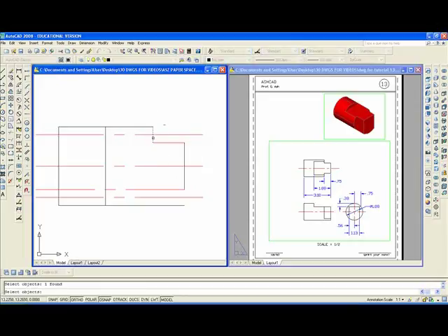copy this line down. There's a lot of ways of doing it. Don't worry about how you do it, as long as you get it done. F enter. F enter again. Fillet it again. Here and here. And I think I can erase this line. I must add 2 lines there. Maybe 3 lines.